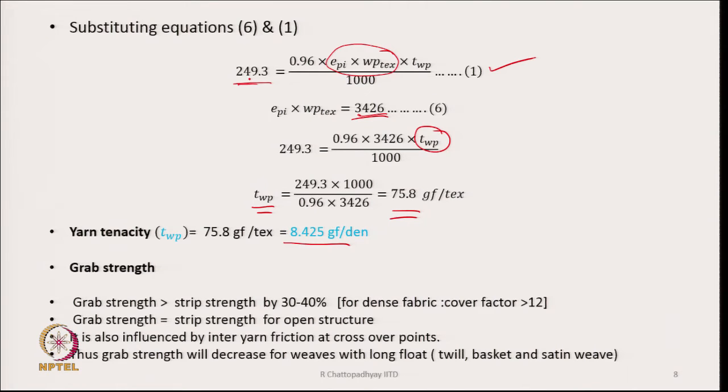Here we need to write a few more points. Sometimes grab strength generally is greater than strip strength by 30 to 40%. This has been stated by some researchers, for cover factor greater than 12, and for very open structure grab strength and strip strength are almost the same.